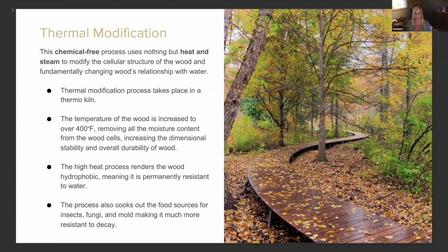It's a really good alternative to composite decking, where composite gets really hot and you don't want any maintenance. You can offer thermally modified wood in your projects, let it weather and go gray, no maintenance. It's going to get a lot less hot.